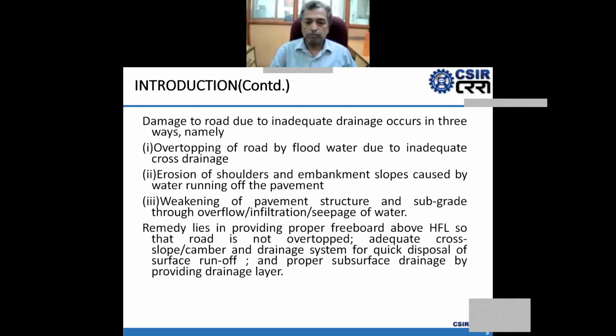Cross slope, camber and a drainage system for quick disposal should be provided to dissipate the surface runoff water, and proper subsurface drainage should also be provided.